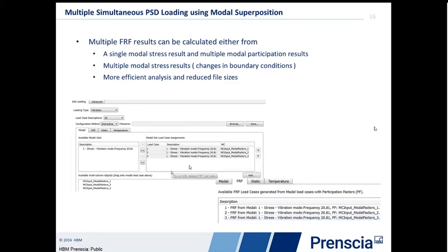The next step of the analysis, I take those 3 FRFs and I pair them up with a series of modal coordinates, PSDs, and cross-correlation. Again, if I have 3 FRFs coming in, I'm going to have 3 applied PSDs and 6 sets of cross-correlation matrices, and things start to be, again, fairly difficult in terms of keeping and managing the data.